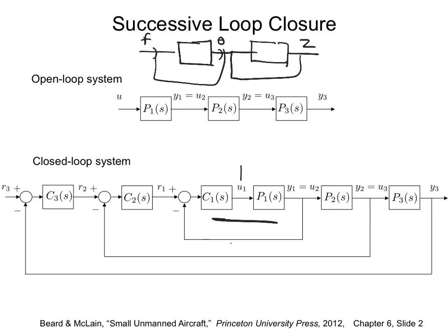if you want to change the heading of the UAV, you roll. So change in heading is much slower. If you want to change 90 degrees, it will take a couple of seconds, and that should be slower, and it's on purpose. Because it's an under-actuated system, I'm not directly controlling the heading. You have to roll first and then your heading will change. So you purposefully make change in heading slower, and then you make this roll angle much faster.